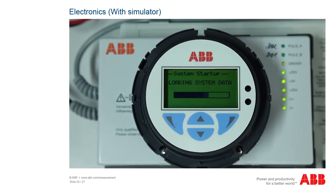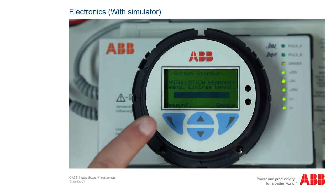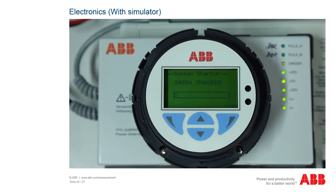Once the simulator has been switched on and the check starts, the flow meter sensor asks what has been replaced. Answer this question with transmitter. All specific system data of the transmitter is uploaded from the memory board of the simulator. No transmitter data or sensor data is deleted or changed. Only the measuring point area data is checked.